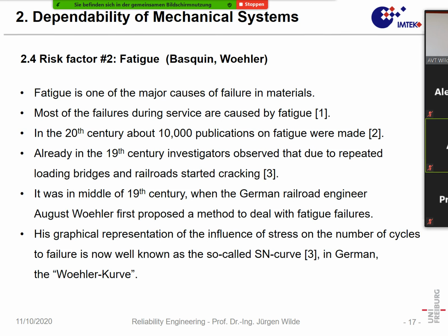So cracks are bad. Cracks in combination with fatigue are worse. So fatigue is one of the major causes of failures in materials, and most of the failures during service are caused by fatigue. That means it is not the unique overstress in most cases, but in most cases it is just the repetition of stress, for instance, or stress concentration.